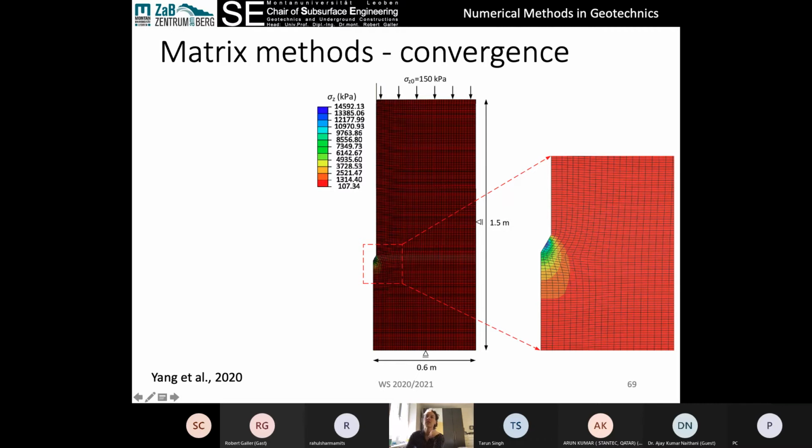This is part of the matrix solving technique, where all of the forces on all of the nodes are being solved simultaneously. And the model is checking that the forces acting on this node in this direction, in this direction, in this direction are all balanced so that the movement is constant and there's no acceleration. So F equals ma, Newton's law of motion, requires the forces to be balanced therefore for no acceleration to occur. So this is then usually the stop criterion for matrix methods, so finite element methods, for example.